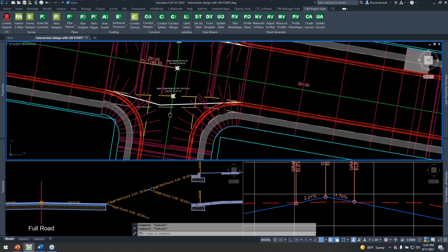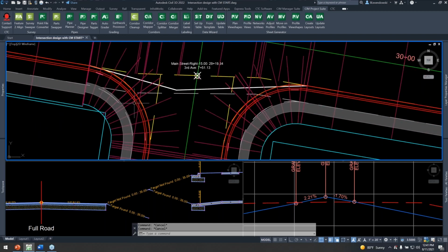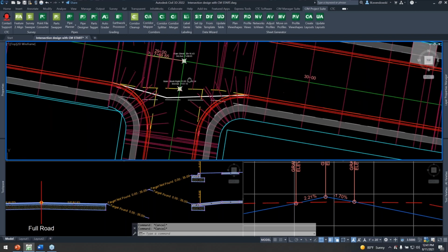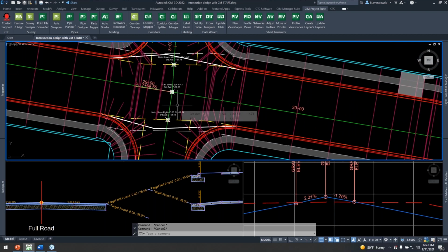All right, let's start. We've got a number of things. We've got to get ped ramps in here. We've got to manage our sidewalk around here. We've got to match into the center line here with our drive lane, and we also have to tie into the edge of travelway alignment right here. And here I want to use something else. We've been linking by layers and styles.